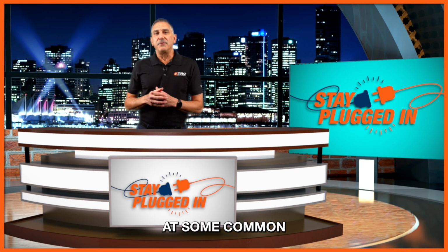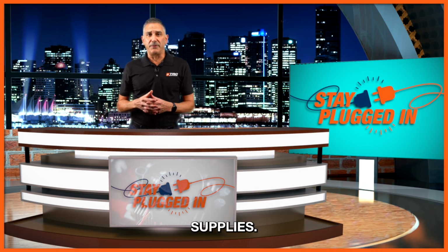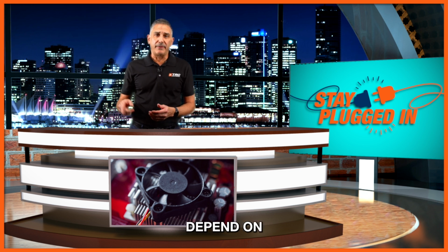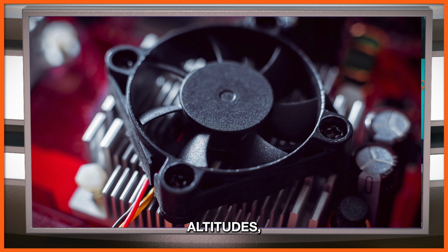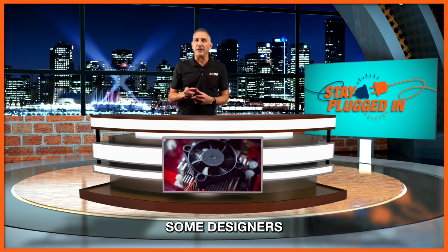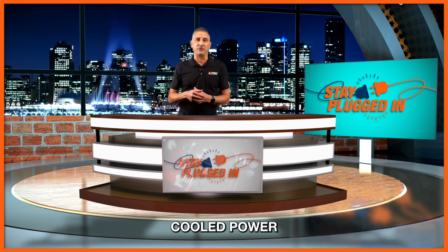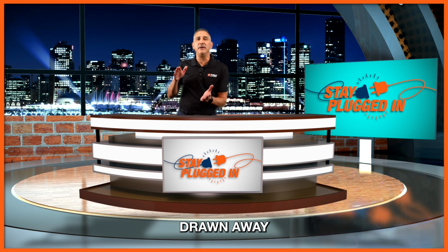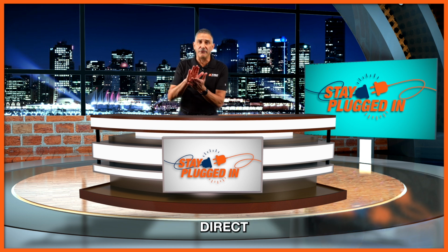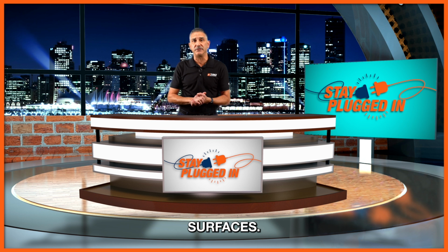Let's look at some common cooling methods of power supplies. Many power supplies depend on air cooling, for example using fans, and at higher altitudes, because the air is thinner, a fan might not cool as effectively as it would at sea level, which would require a design that accounts for these conditions. Some designers may consider conduction-cooled power supplies for those applications where heat can be drawn away from the power supply using direct contact with cooling surfaces.